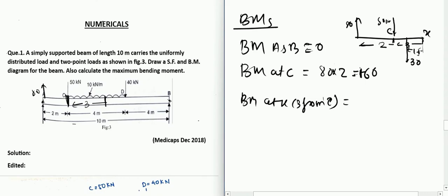So this is the FBD on the left. Let us just calculate the moment here. The moment will be 80 into 2 plus 3, which is 5, because the 80 into 5 was in the clockwise direction, and we are calculating on the left side of the beam. That is why that is positive. The 50 into 3 here is in the anti-clockwise direction, because of this point force.